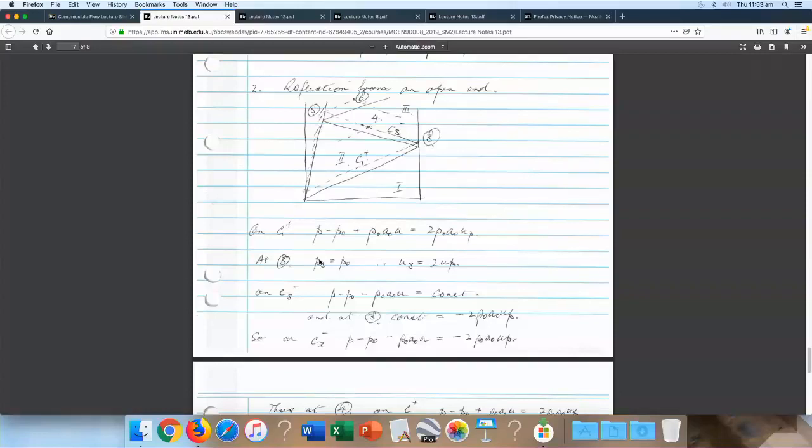and then I'm taking a normal component, which may be subsonic, but if it's not, if it were perpendicular to the flow, then I have no supersonic flow solution. Why? Because if I had a supersonic flow, I know that if it were one-dimensional and I'm coming along here and the fluid has to come to rest at that body somewhere, it's going to have to diverge.